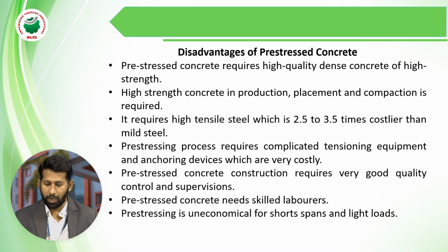So next, disadvantages of prestressed concrete. Prestressed concrete requires high quality, dense concrete of high strength. High strength concrete in production, placement and compaction is required. It requires high tensile steel, 2.5 to 3.5 times costlier than mild steel. The prestressing process requires complicated tensioning equipment and anchorage devices, which are very costly.